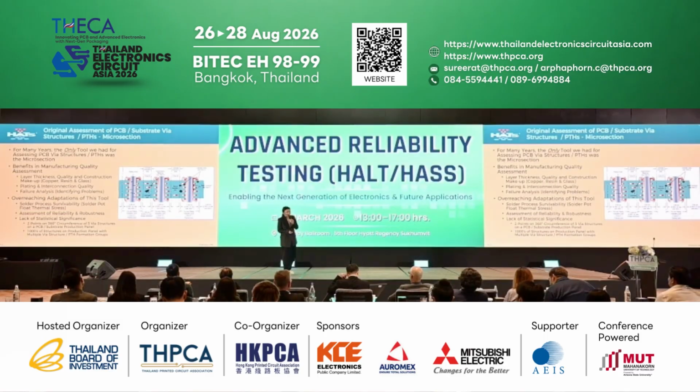And on one microsection, you can only test typically 3 vias. Sometimes a very skilled person can do 7, 8 vias, but that's about it. And for small vias, it's even more difficult. A lot of times, a skilled person can only do 1 for some microvia structures.